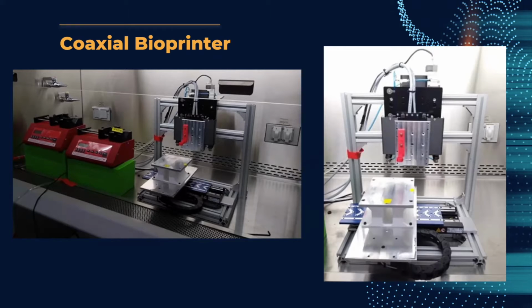Basically with our computer, we will determine the rate at which we want the material or the syringe to be extruded. And then we also can choose with this base plate over here where exactly that's going to move, so we can manipulate where that material will be placed when printed.